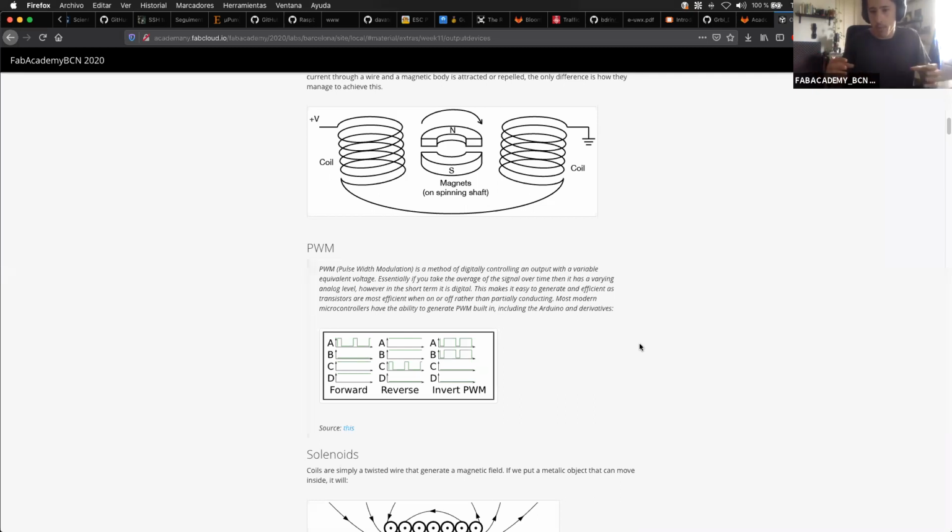The inner part of the motor that is rotating is called the rotor. The outer part is called the stator. So the rotor has an inertia, and sometimes it's a little bit difficult to overcome that. How can you counteract that? Either you help it by hand, or you put more current. But putting more current sometimes is not easy, because your electronics or your circuit cannot give you more current because it's limited by that. So you have to help things a little bit.